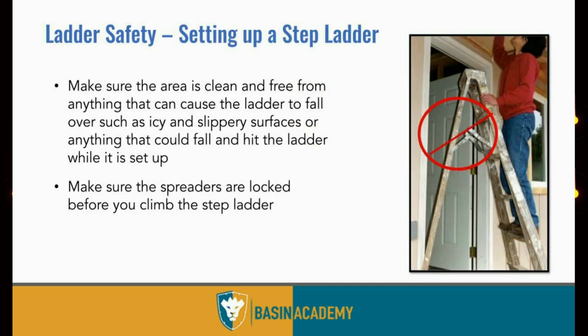Setting up a step ladder properly. Make sure the area is clean and free from anything that can cause the ladder to fall over, such as icy and slippery surfaces, or anything that could fall and hit the ladder while it is set up. Make sure the spreaders are locked before you climb the step ladder. The spreaders are the ones between the front and back legs of the ladder, and as you can see on this illustration, this guy does not have his spreaders locked. Bad idea.